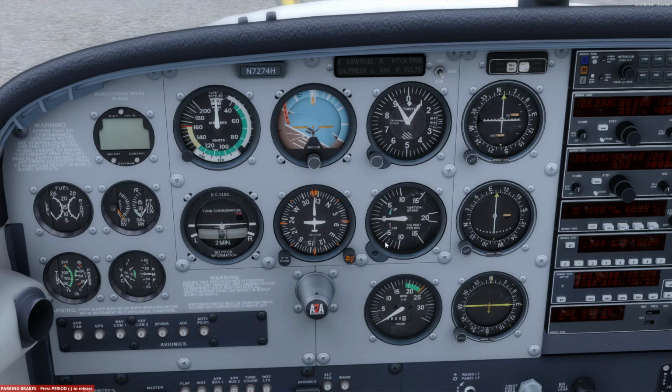Tells you how fast you're going up or down in hundreds of feet per minute. So if this arrow is pointing to the 5 down here, you're going down 500 feet per minute. Next is the heading indicator. It's an instrument that you manually have to set to whatever the compass heading is, and then there's a nice heading bug on this one to give you a nice visual reference of what course you're supposed to fly.